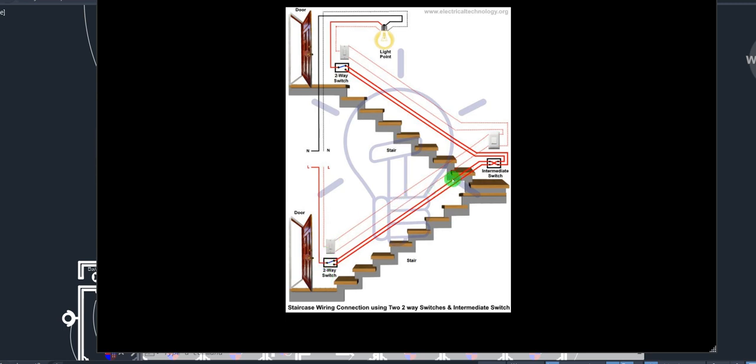I can also activate at the second place. That is why it's two-way. One way is this. The second way is this. I can turn on from here, I can turn off from here. So that is why it's called one gang two-way. The name two-way originated from controlling the point from two points. The name one gang originated from the switch in question having only one button. Because it has one button, that is one gang. Because it's two-way control, that is the meaning of two-way.